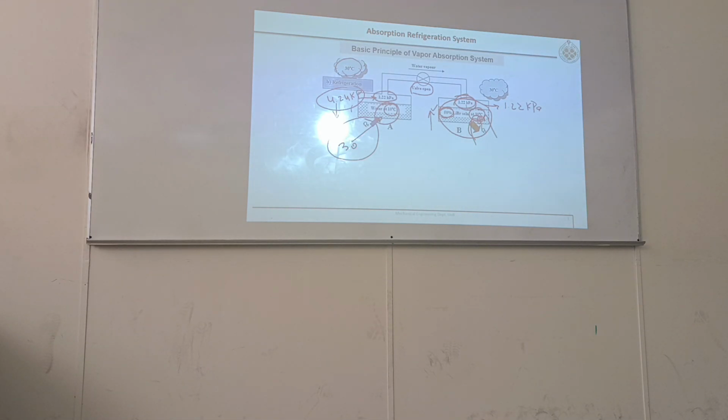So it's not a continuous cooling. Cooling, regenerate the water, bring it back again cooling, again regeneration. What does regeneration mean? We will heat this solution so that water is evaporated. Lithium bromide has a higher boiling point than water. So when you heat, only water will evaporate, lithium bromide will stay there.